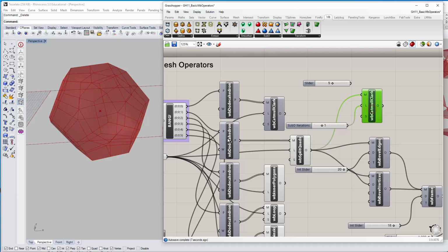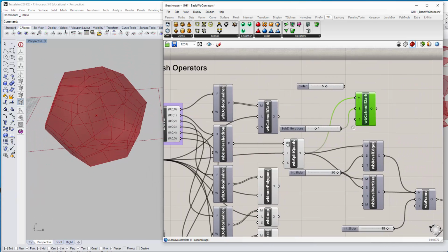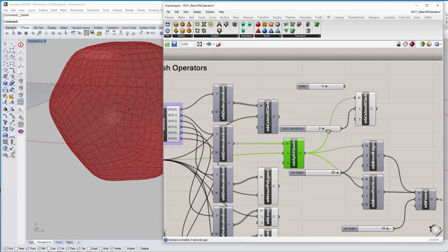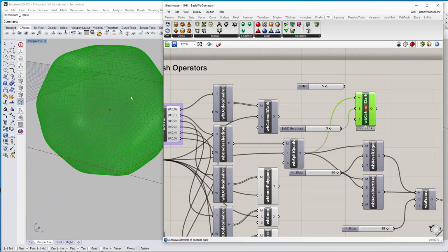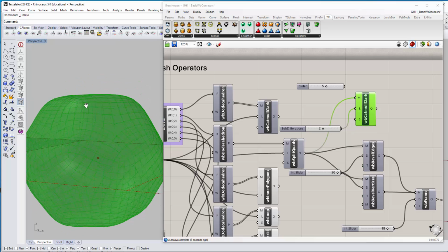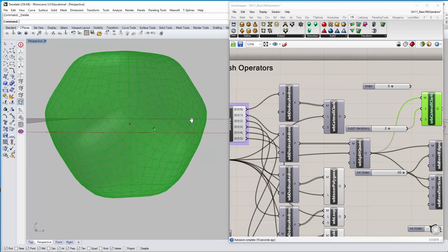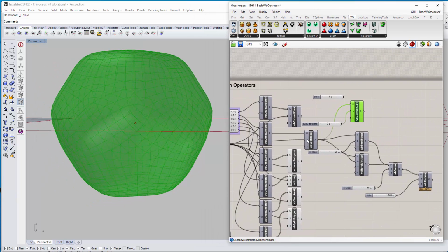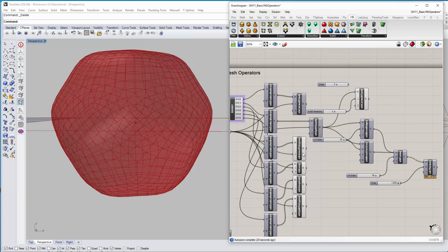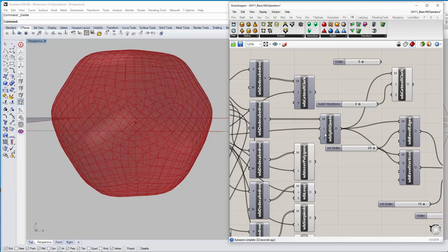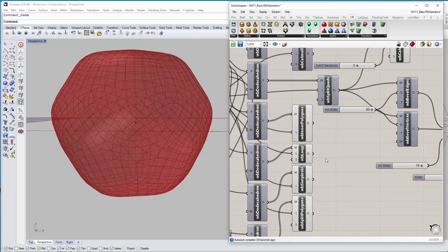We know the original split quads does this, and maybe that's one iteration, but you can actually push this into a Catmull Clark, which would take that and apply a Catmull Clark to it. You can mix, and you'll see that it gets softened or rounded out a little bit, right? While still having a little bit of the polygonal faces, albeit a little bit relaxed. So the main idea is that you can mix and match all of the sub-D ones. They're easy to work in between. You can do the split quads after Catmull Clark, or two Catmull Clarks end to end, whatever. Or do a Weaverbird loop